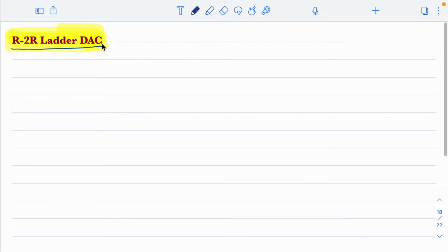Right. So here I'll take a 3-bit DAC example, and with that I'll explain. As the name suggests, in this digital to analog converter we use two resistors. One resistor of value R, and the other will be 2R. The input data is digital, and based on the digital input we'll be routing the connections, and the output is taken with the help of an op-amp.